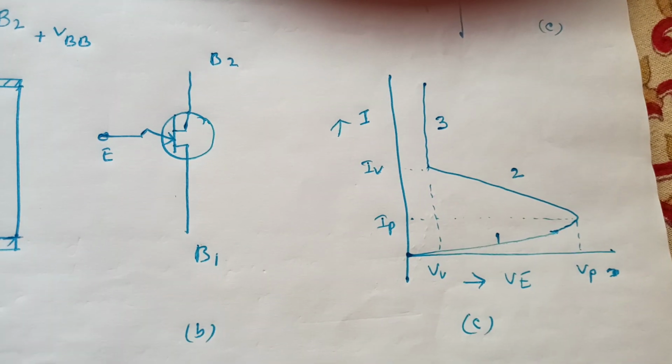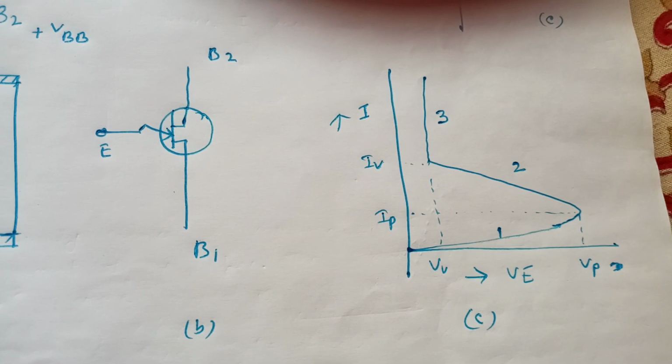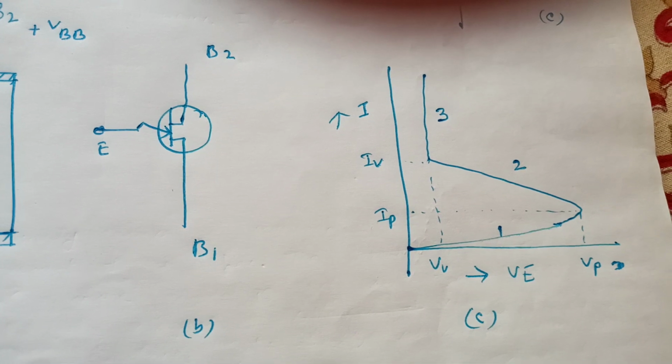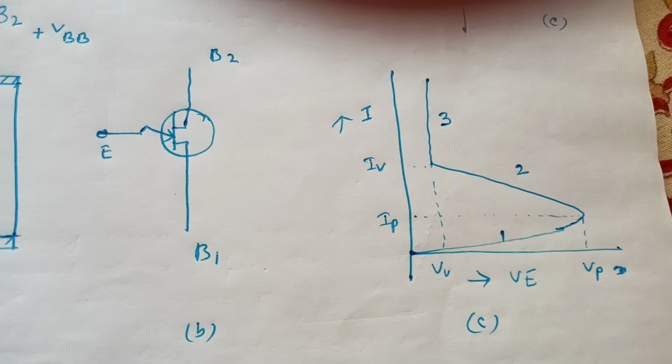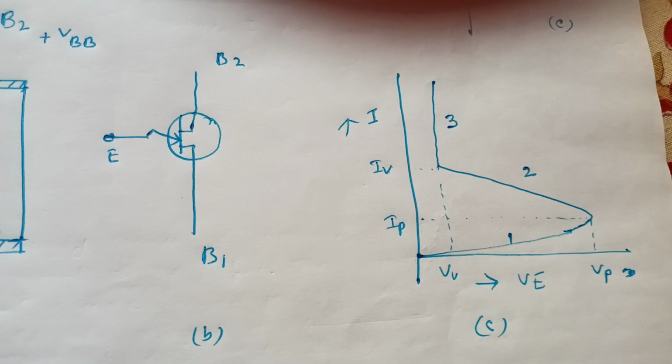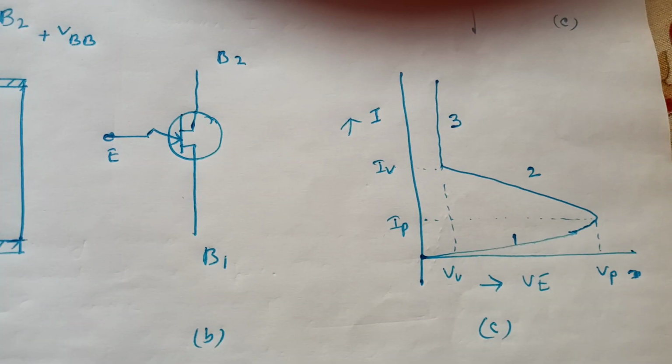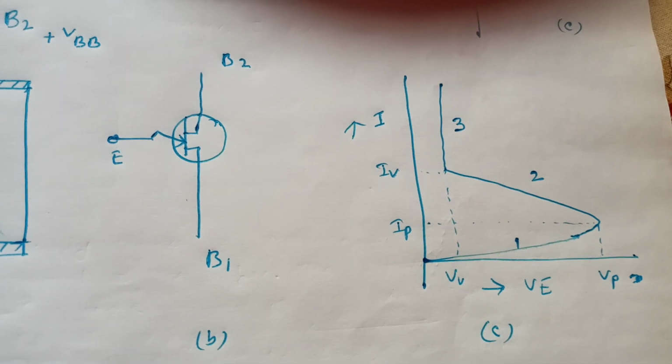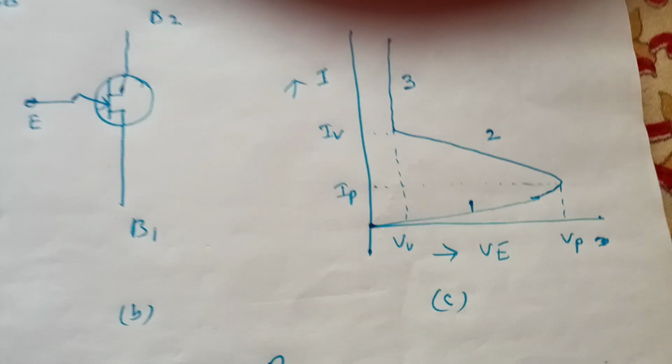The difference is that the switching in a thyristor originates from regenerative transistor action, but in the UJT it arises from conductivity modulation in the negative resistance region.